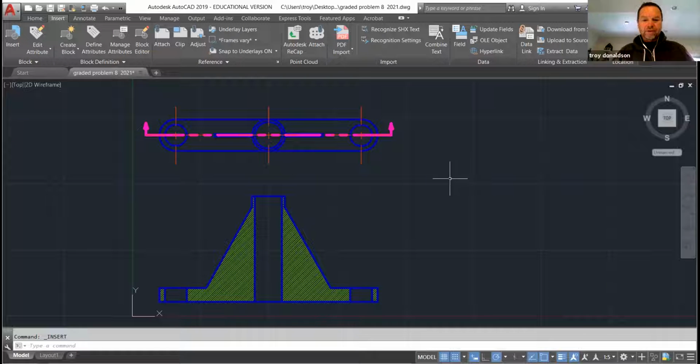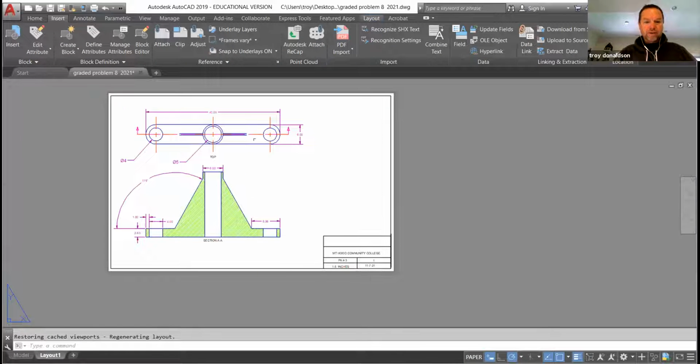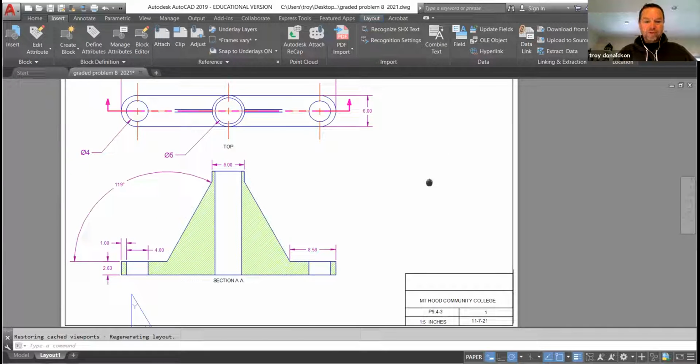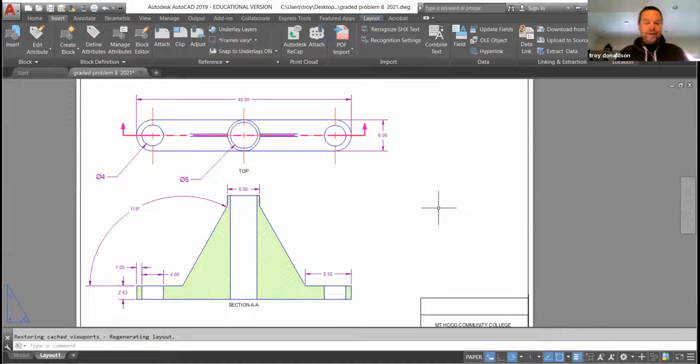And then, of course, the polyline arrow, nice thick cutting plane line. That's great. Remember that it's always more dramatic here than it is going to be in here. So this is where you want to view it, and you want to kind of zoom into it and take a look at it. Now, that hatching looks a little too dense. So we probably need to change that and open that up a little bit. It's not supposed to look like a fill. It's supposed to be lines.